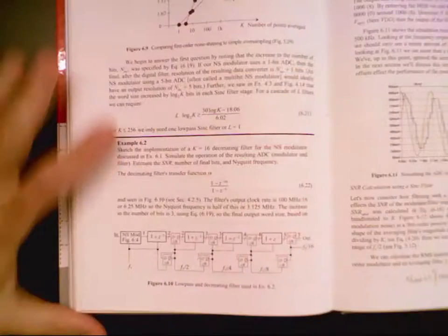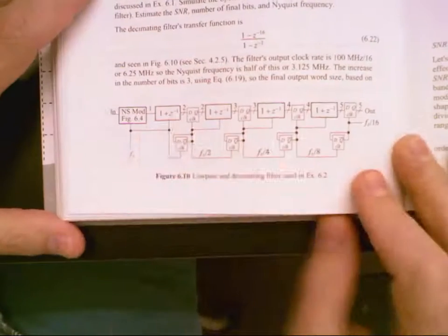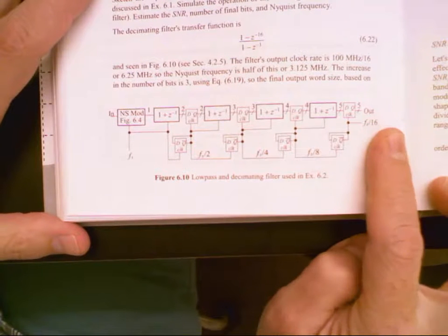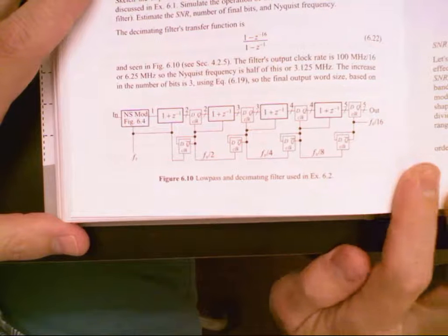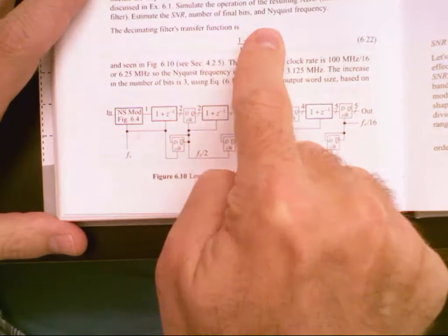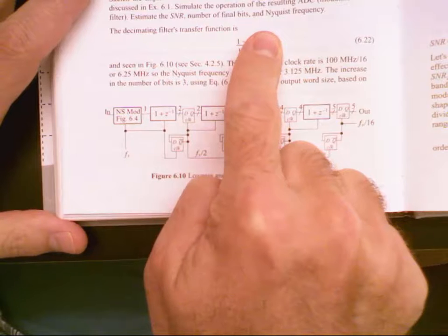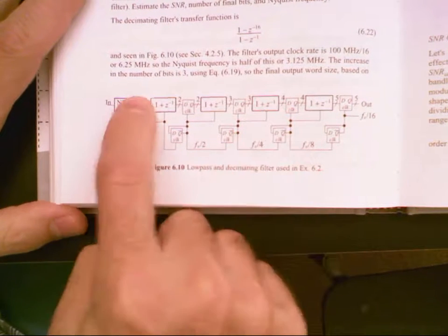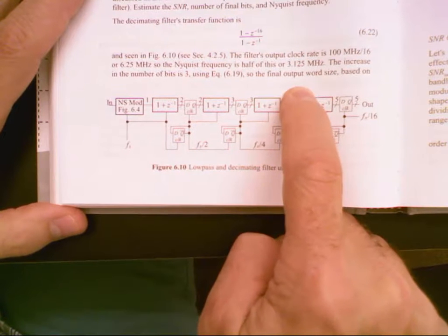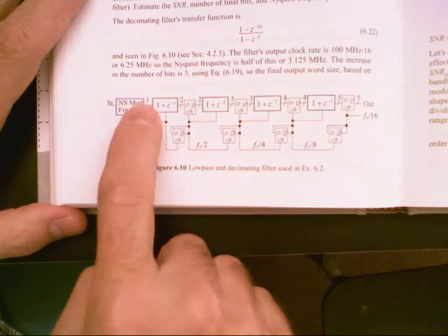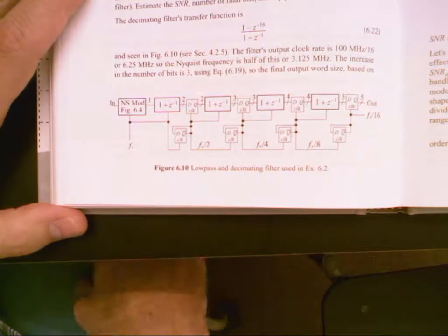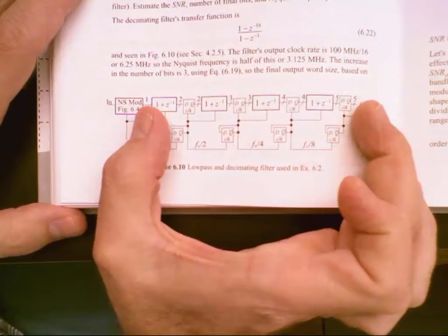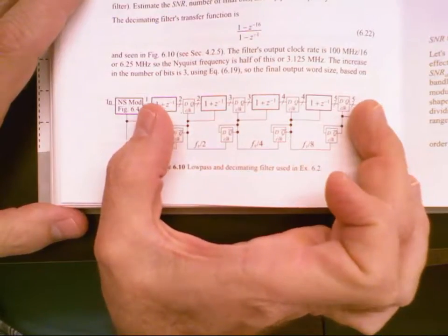Now, before I show you the simulation, tell me what I'm doing here, just as a sanity check for myself. Yeah, I'm decimating and filtering at the same time. So everybody sees what's the point of these registers? To retime the data so I don't get a race condition. So just make sure that, because there's a 1 here, that it doesn't fly through. Okay, does anybody not see how this equation is implemented at this point with this digital hardware here?